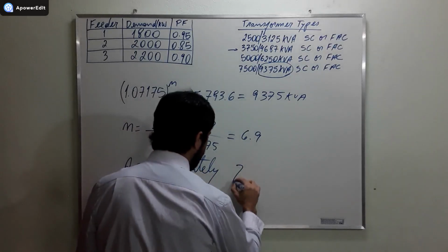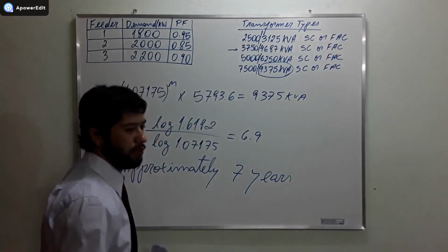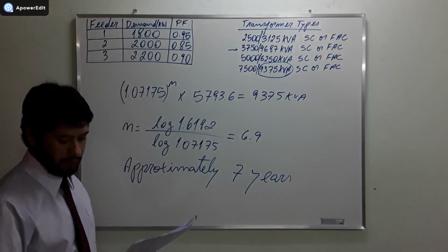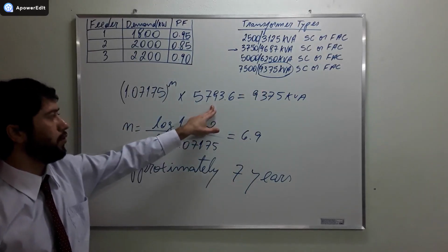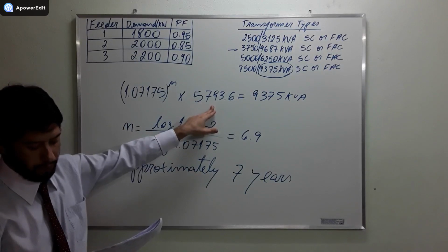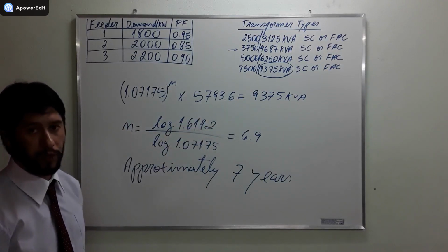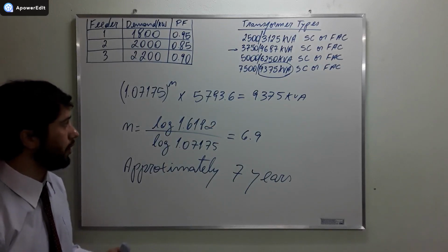Approximately 7 years. Okay, so this is our final result. Ultimately, this transformer here, based on this maximum demand, will be loaded to its fan-on rating in about 7 years, okay?